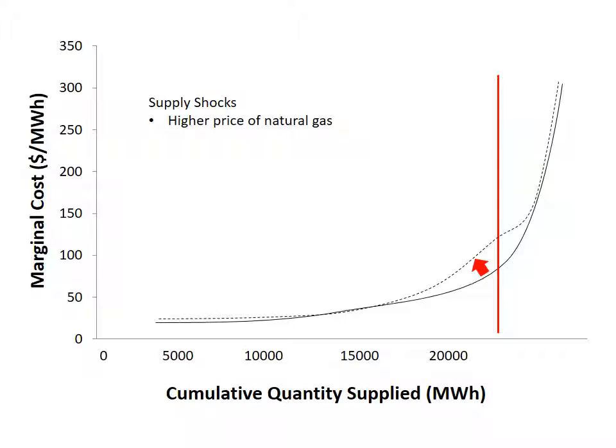So fuel prices, remember, the amount of money, or the fuel costs, that a generator has to pay for fuel is directly related to its heat rate, so the efficiency of the power plant, and how much electricity it's producing as well, but also what the price per million BTUs of fuel is, and we could talk about natural gas in this case, or coal, or oil.